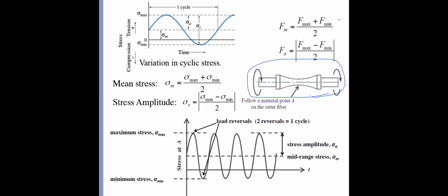So I'm gonna skip this. I think you must be familiar with that, right? If we already know the maximum force, then we can convert it to the maximum stress, right? Similarly, we can get its minimum stress. And this cyclic loading is just repeating periodically, right?